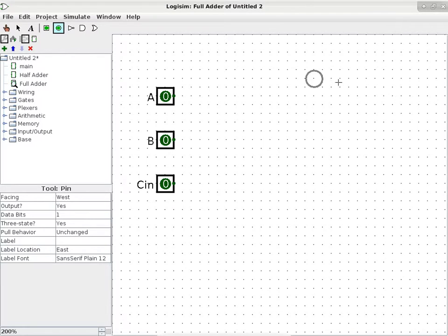The output pins, the first one is just going to be the result here. So I'm just going to label this one as R. And the other one is carry out, okay, because we need to send the carry to the next column. So this is C out. So now the question is, how do we work with the input pins so that we have the output pins? The carry is the one that is a little bit more complicated. We'll deal with the result first, okay?